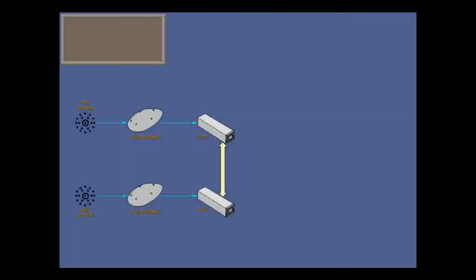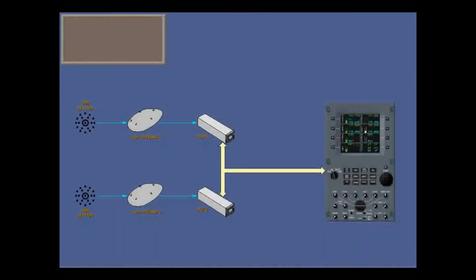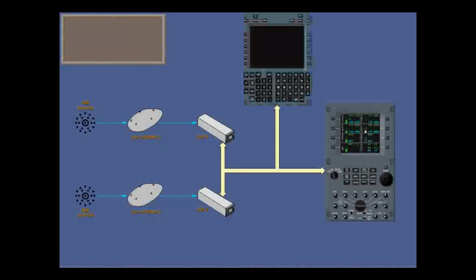The Automatic Direction Finding ADF system gives automatic point-to-station bearings to a fixed non-directional beacon. ADF receivers 1 and 2 are tuned by the ARC2 or remotely by the FMS.